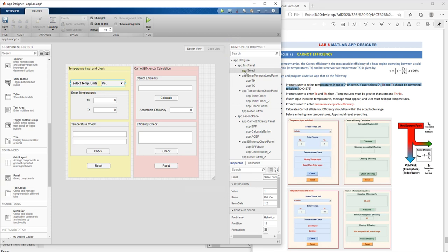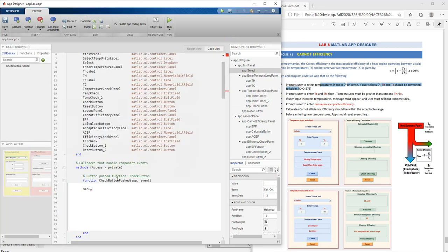So we have to write the name app.select.value. Let me go to here, write app small letter dot select. If I write S, it will give me options. I will select the first option. Dot V, take the first option, which is value. Now what will happen? Matlab will go to this variable in memory. It's a structured variable. Take the value and assign it to menu.